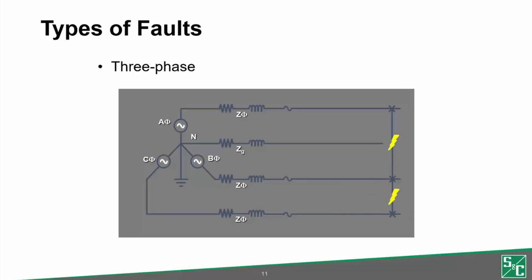In a symmetrical system, this condition would result in the largest magnitude of fault currents. And when we are doing an overcurrent coordination study using time current curves, TCCs, the two main faults that we have to analyze and ensure are covered by the TCCs are the three-phase fault and the single line to ground fault. The three-phase fault, because it's usually the largest magnitude of fault current that's seen.